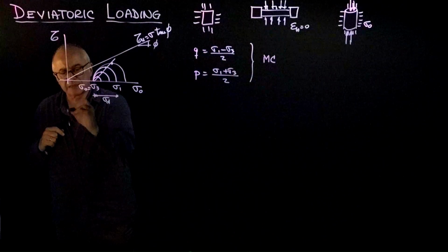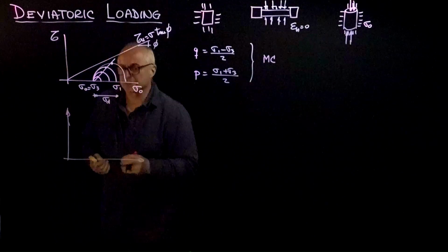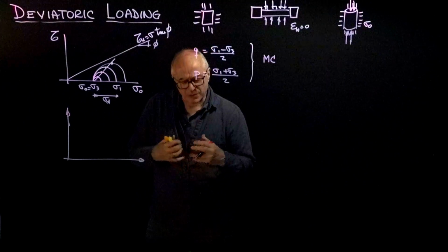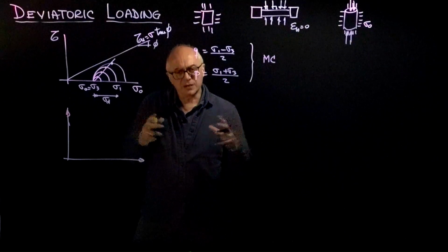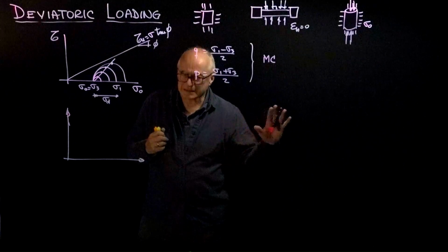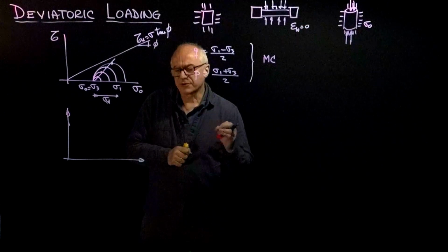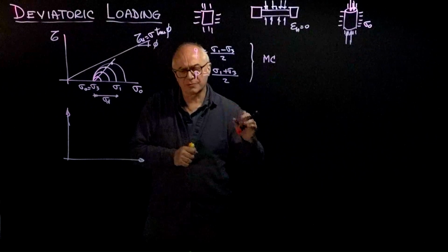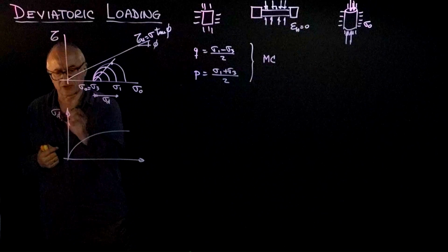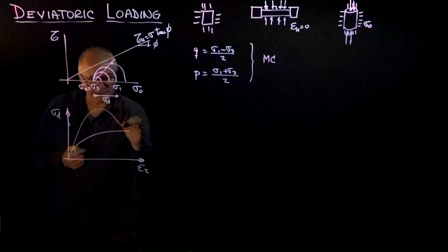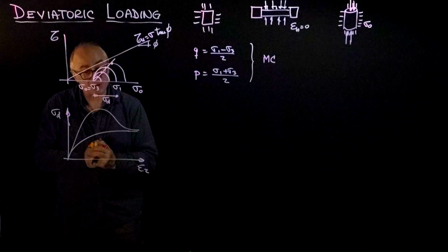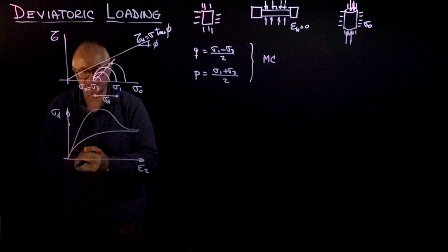The second observation is that the triaxial device was developed in 1932 through 1936 by Casagrande and used first by Terzaghi. One of the things that Casagrande was able to observe was that during loading, the specimen was changing volume. That was not clearly observed in the absence of a triaxial test, to some extent in shear, but not so effectively. And therefore, he recognized that materials change volume, but it depended on how dense they were at the beginning. So if he took a loose specimen, it would behave like this under sigma deviatoric versus epsilon z, but a dense specimen would behave like this. Eventually, at large deformation, both of them would reach a similar asymptotic strength, while the dense specimen had reached a higher value, which is the peak strength.